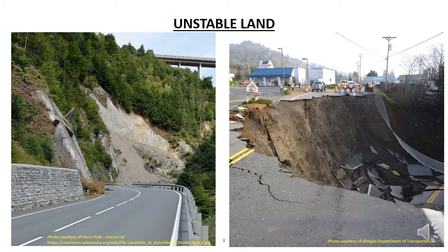Rebuilding the slope involves excavating the soil back to a stable soil formation and then rebuilding the slope in layers. The excavation involves constructing benches and shear keys in a stable soil that allow the new fill area to key into the existing stable soil and make a stable slope. We'll look at this a little bit more in later videos.